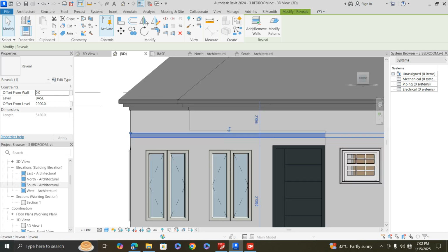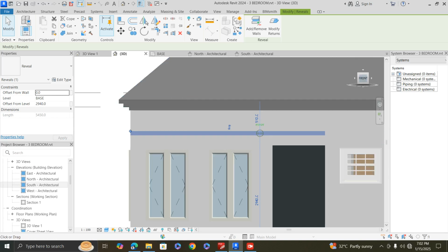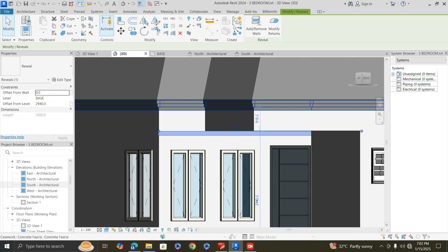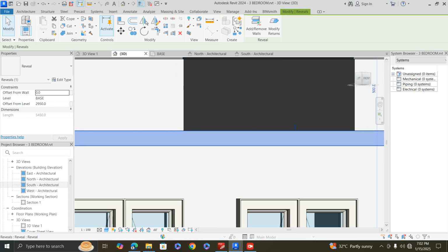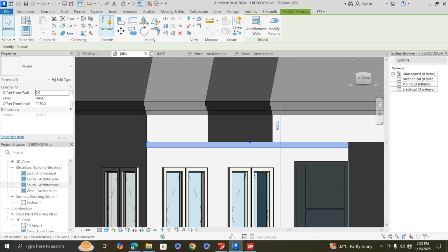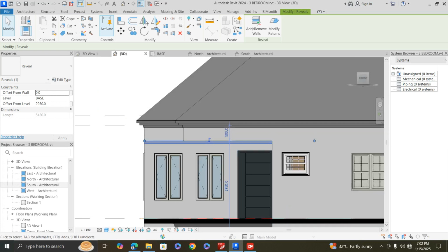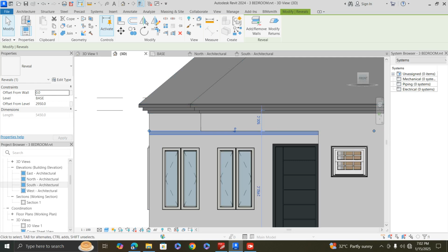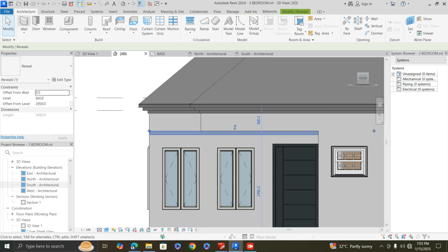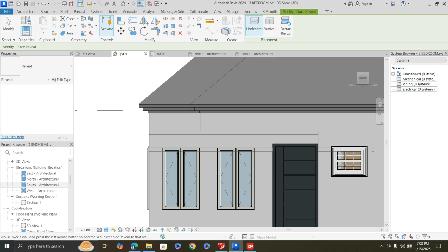Good. So I'm going to make use of the front elevation. I want to move this up a bit. Just right to the base of my beam. Perfect. So I'm going to copy this. I'm going to copy, or better still, you can still click on wall reveal. You can still make use of wall reveal. Click again, then drop at interval.